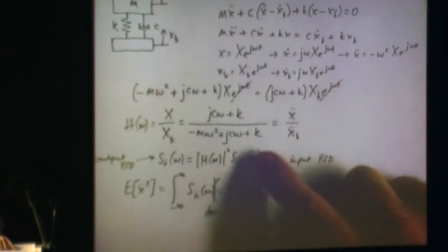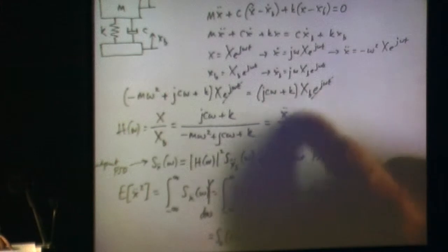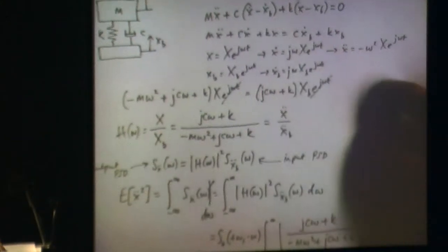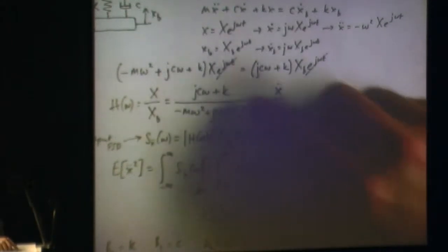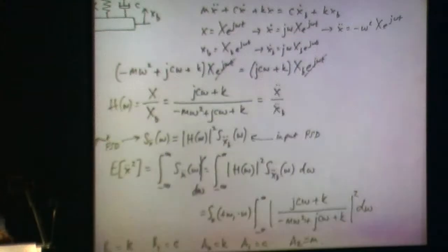I plug them into this equation, I get this situation. The exponentials will cancel, and if I put my output over my input, I get my frequency response function, okay? Complex frequency response. And so there's my relationship, and that's the same relationship if I'm dealing with accelerations, which I am doing in this problem.